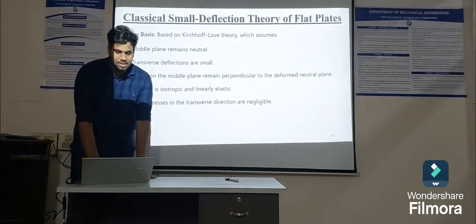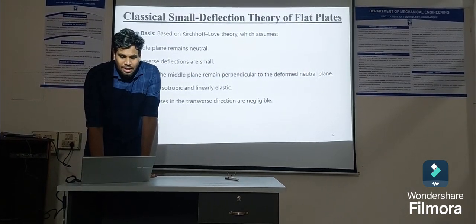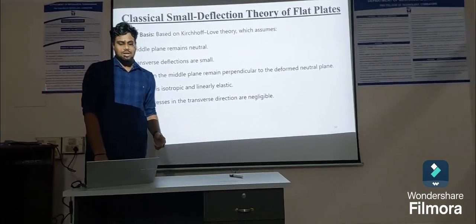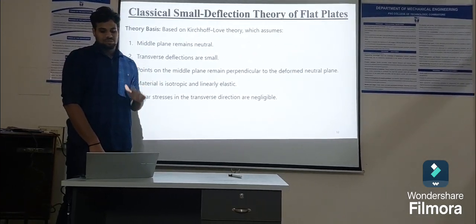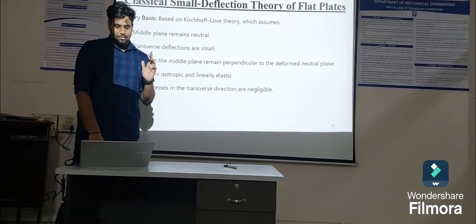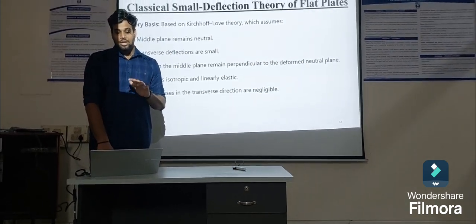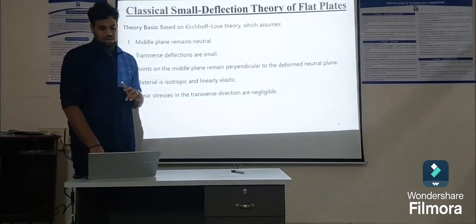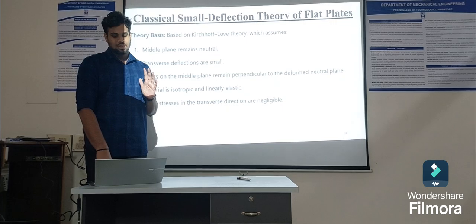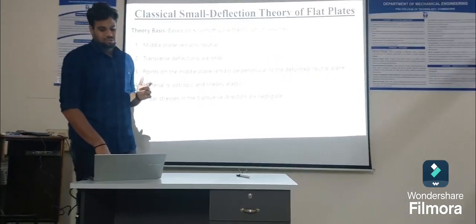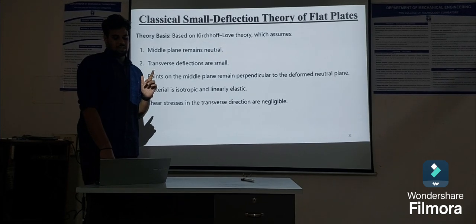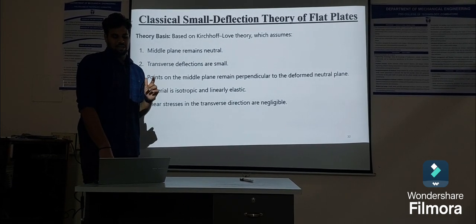Classical small deflection theory of flat plates. The theory is based on Kirchhoff-Love plate theory, which assumes first, the middle plane remains neutral; second, transverse deflections are small; third, points on the middle plane remain perpendicular to the deformed neutral plane; fourth, the material is isotropic and linearly elastic;